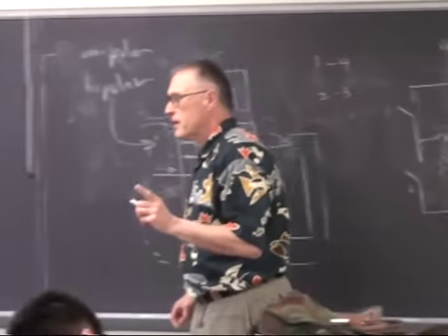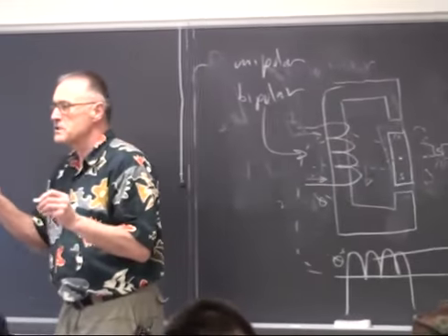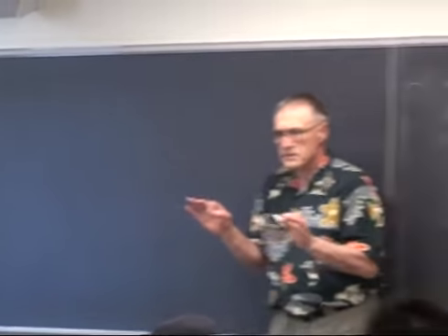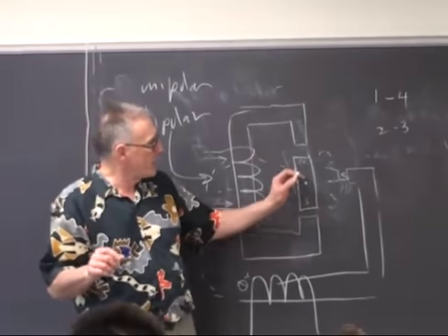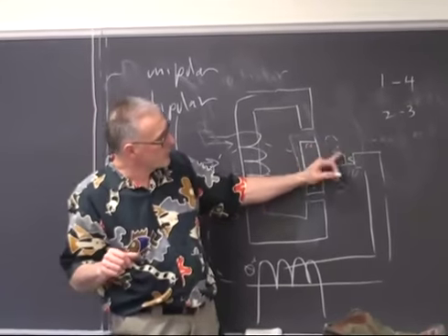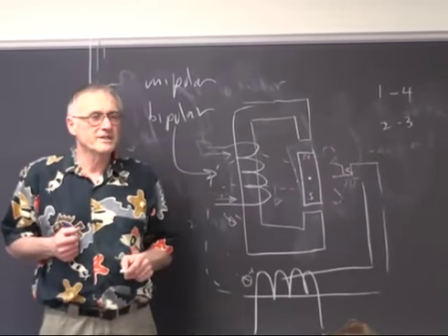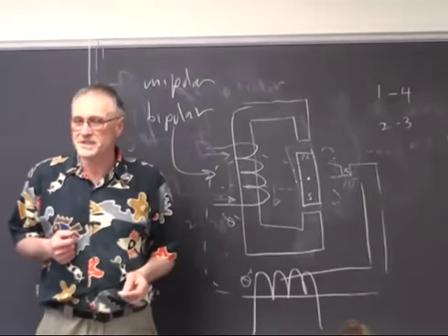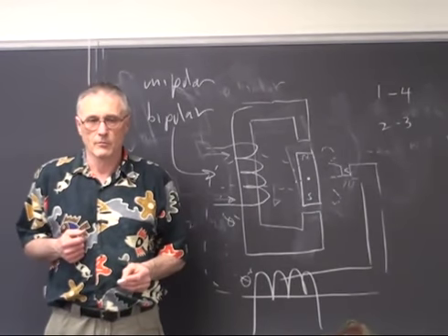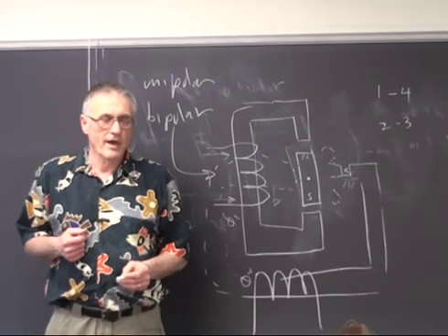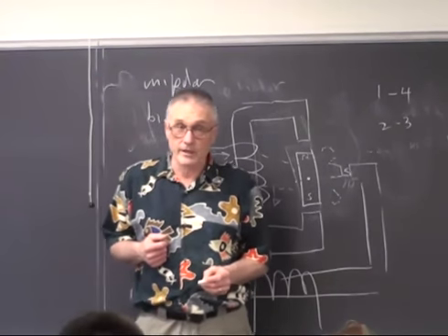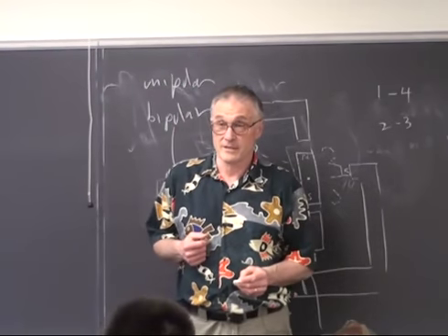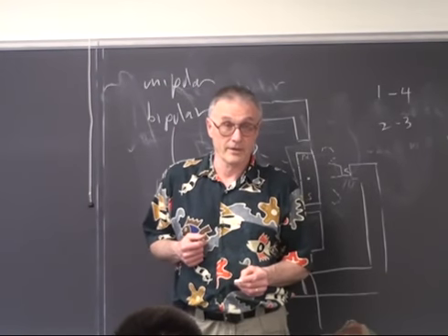This brings us to a very basic limit. As long as you stay below a certain torque level, as long as you stay below the torque that the motor can generate, the motor is digital accurate. It will go exactly 1 step per pulse. No more, no less. If you have the motor try and produce more torque than it can produce, then it'll start to slip phases, and it'll no longer be digital accurate.